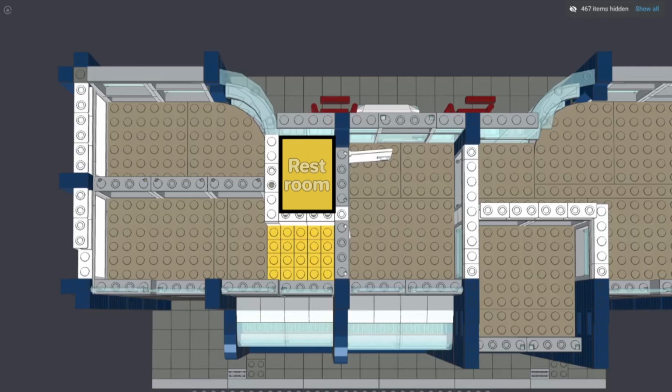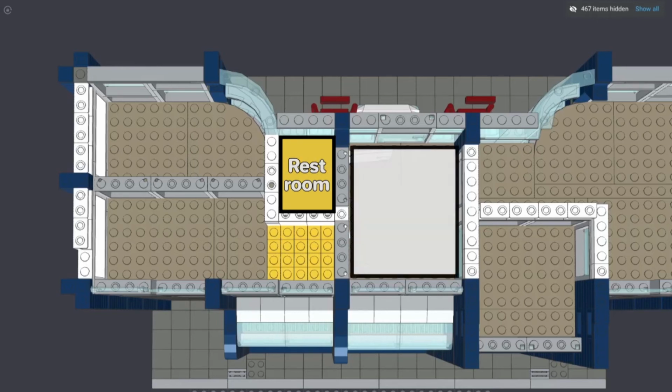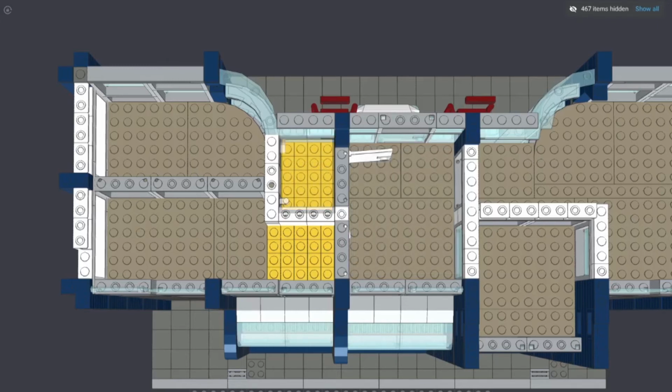So it turns out to be better to put the restrooms near the centre of the building, where there is a lobby or circulation area, and that uses less space and simplifies the layout. I tried out several ways of doing this, and the best place turned out to be at the back on the left-hand side of the lobby. This is best because the layout of most floors isn't quite symmetrical, and putting the restroom on the left-hand side gives me better proportioned areas on the right-hand side.